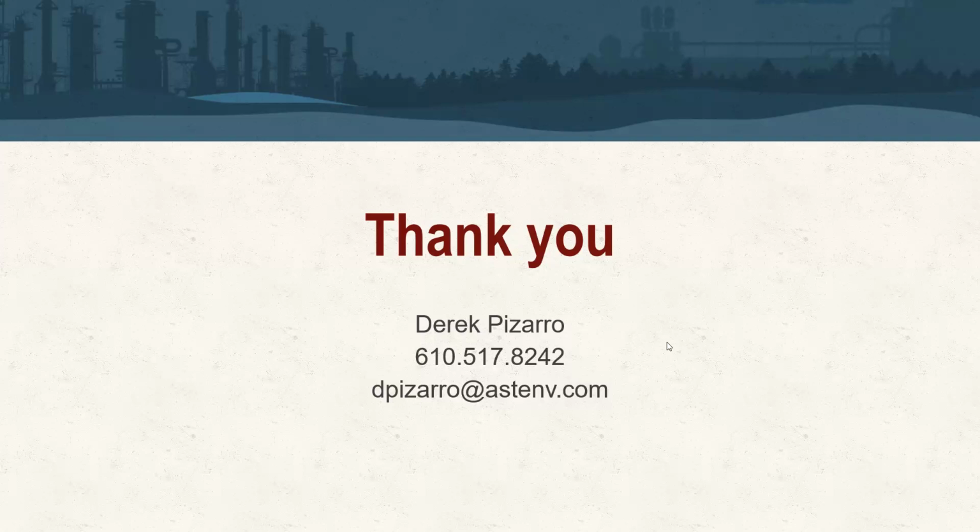It could be something as simple as, at the outset, I only have the ability to take one composite sample of soil and send it off for testing, or I've only got the ability to take so many groundwater samples and have the lab put a dosage array onto it. If you know enough about the site through groundwater or other sampling events, you could say, all right, we should do 2, 3, 4 here, or if we don't know a lot, we should do 2, 4, 6% by weight. Yes, you're going to burn a sample, but they're not that expensive, and it's going to give you some very high level data to start to drill down into.